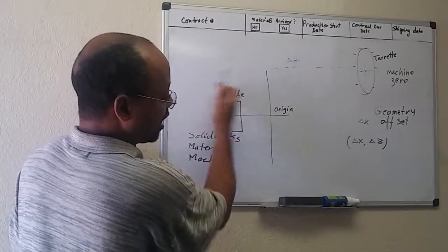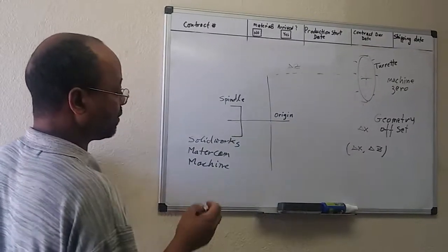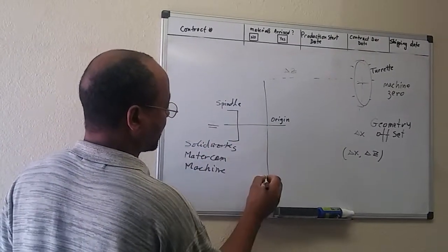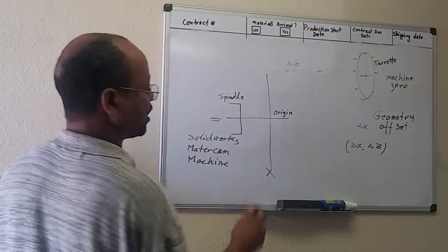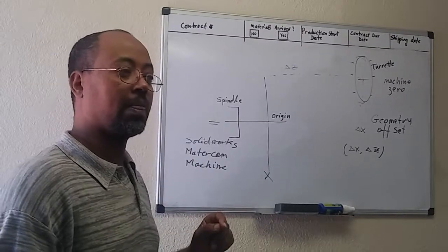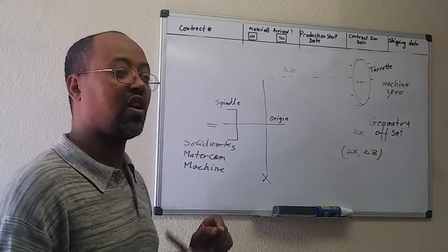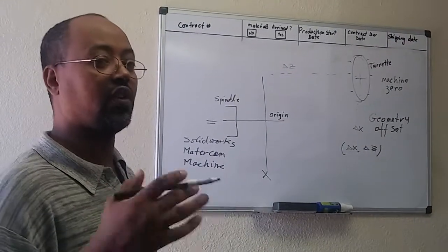My part is on this side. It's actually on the second quadrant of the Z-X axis. This is where you do a lot of your machining. So, question for you. On your program, the values of all the Z movement, do you think is positive or negative?